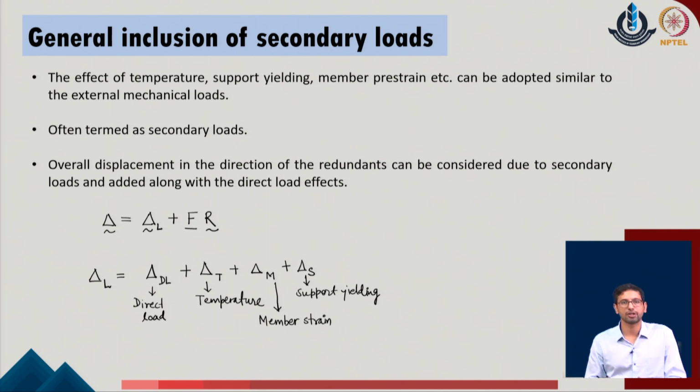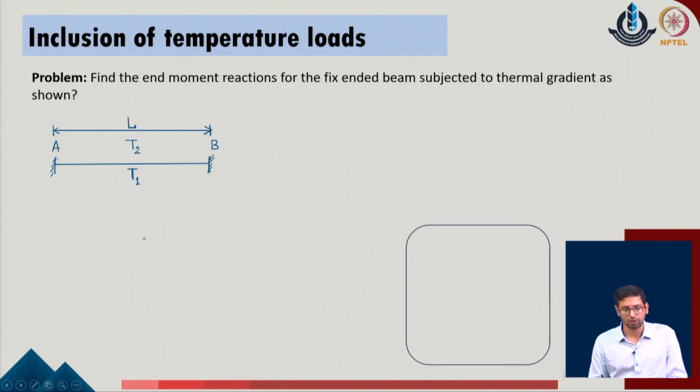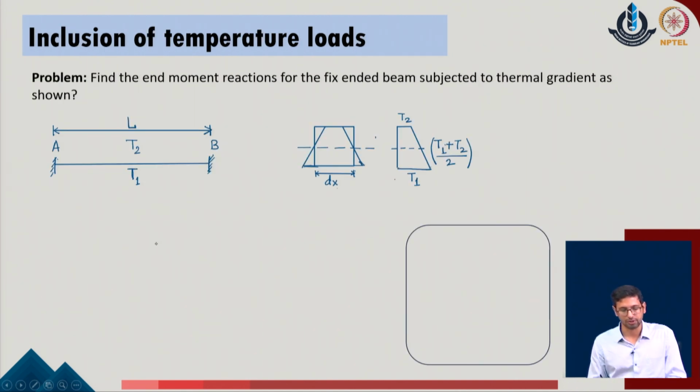We considered one way to accommodate them by considering them in the direction of the redundants which have been selected, so that these conditions become the necessary compatibility conditions of the given system. But in multiple cases, it is not always possible to define these effects in the direction of the compatibility conditions or in the direction of the redundants, and in those situations we need to accommodate those effects as the parameter of the external load in the given system.